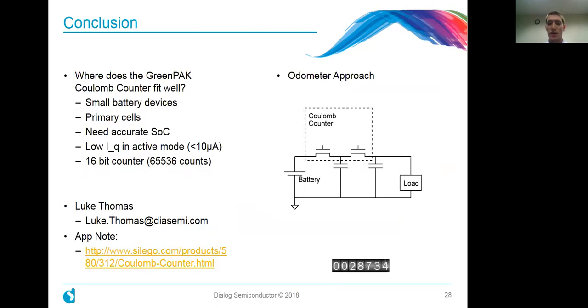You simply have a couple of capacitors externally that you put through 2 FETs, and you pass the charge. You have to understand how much charge is being passed through each time. If you do just a little bit of math and a little bit of control, you can fairly accurately determine how much charge has left your battery if you manage all of these premises well.